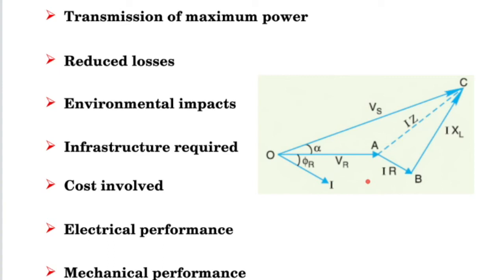So what other things can we get from power factor? Lagging, and the other word could be leading, right? Power factor could be lagging or leading. We can have leading power factor as well. When can that leading power factor happen? When we have resistive capacitive load.